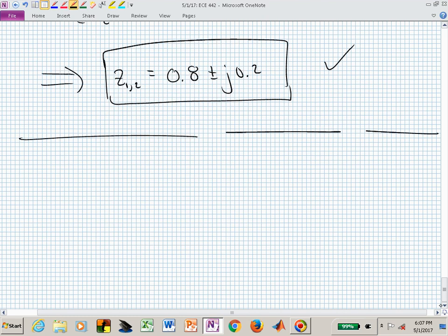What we want to do now is actually sort of step back and say, when will this be possible to do, to locate closed loop poles wherever we want in the z-plane? And that's what this concept of controllability is concerned with.